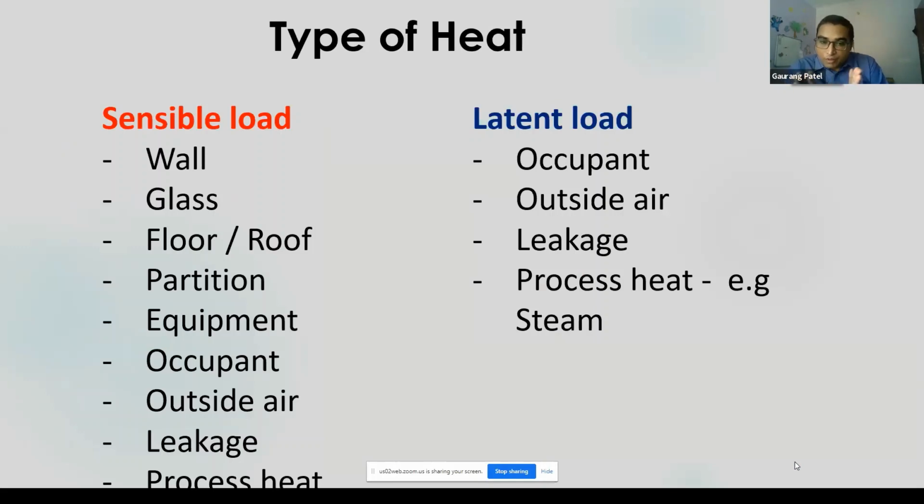in two forms. First we calculate the sensible load, and second we calculate the latent load. Now what is sensible and what is latent? Those students who have a fair idea of psychrometry know what is sensible and what is latent. But in a simpler way, the sensible load is the load which increases your temperature, the load which will simply increase your room temperature.